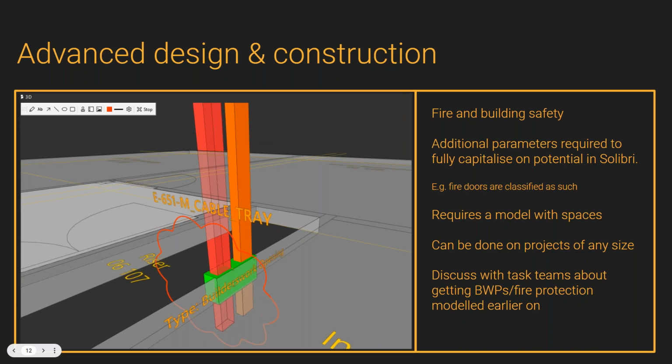Before we move on from fire safety, I'd just like to cover another aspect I've used Solibri for. This wasn't actually using the BIM Coordination Plus extension. This is just using an information takeoff again. What I was doing is extracting the location, size, and number of builders work holes. The reason that was required was for adding into a fire compliance book, which is one of the things that we have to provide to prove assurance during a build.